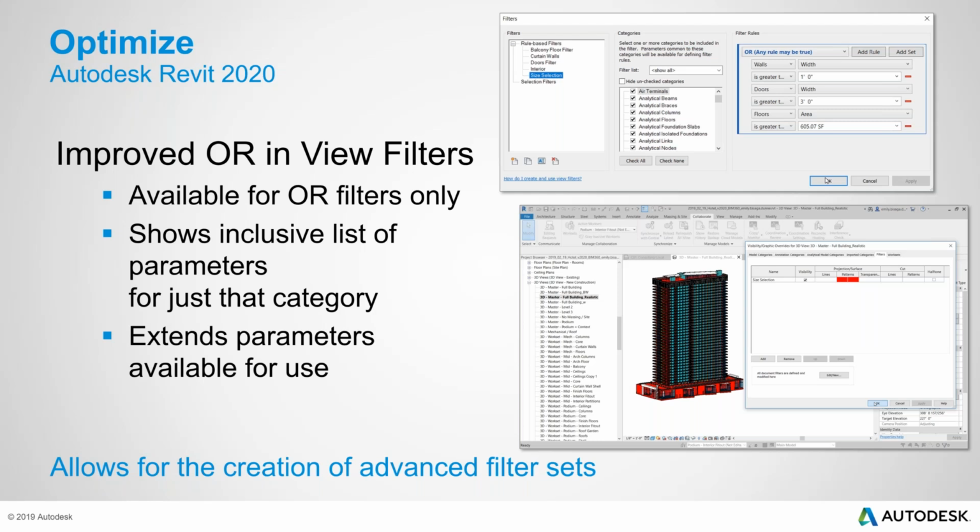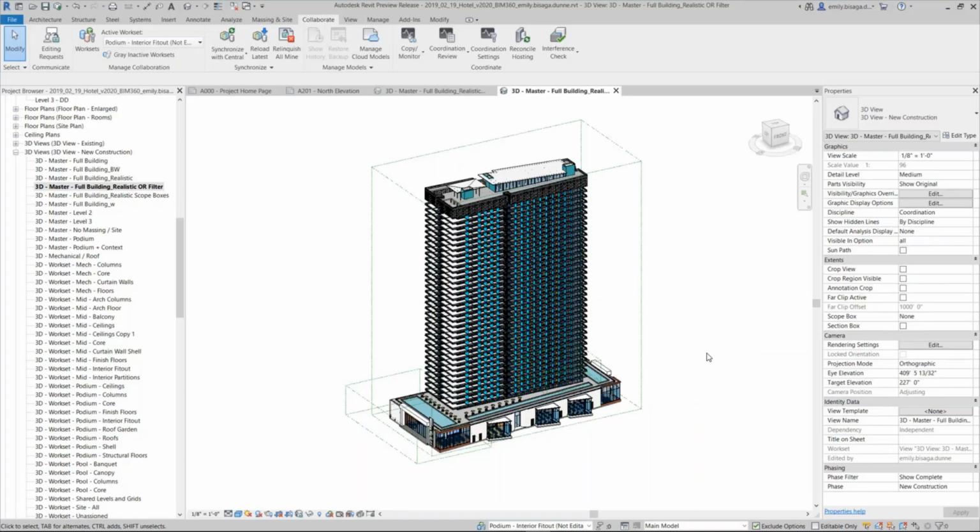So in this large project, if I wanted to identify the walls which are, say, 6 inches wide and whose lengths are more than 6 feet, here I can say wall with width 6 inches and wall with length more than 6 feet. So here you can see it will list down all and I can mark them as red. So with multiple OR features on the filter, I can really list down my walls with multiple categories, so more than one property. It helps me filter out things much easier with more than one property included.